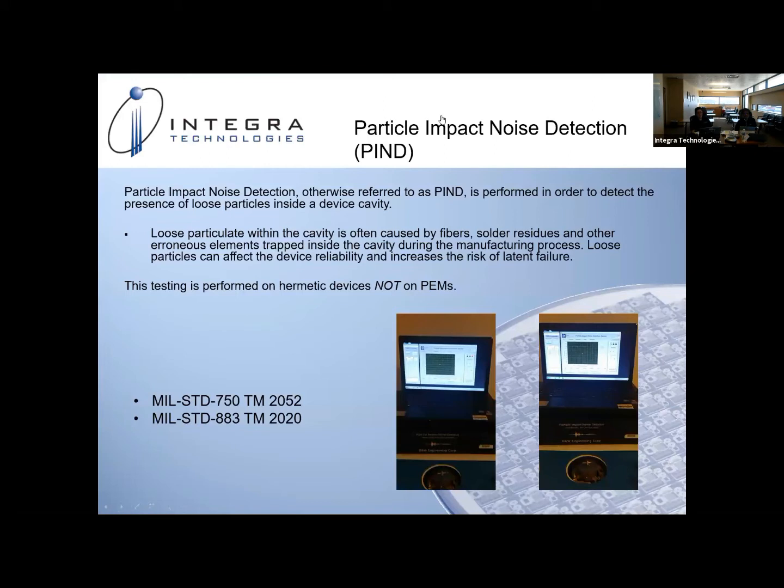All right. So moving on to particle impact noise detection. Again, this is a non-destructive technique. The short word for it is PIND. PIND is performed on hermetic devices to detect loose particles within a device cavity that may have been trapped inside during manufacturing. Several methods of detection are available, the O-scope being one, the audible speaker being another, and the threshold detector being the last one. If you want to play the video there on the left.